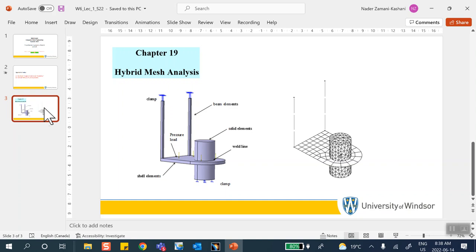Never mind, we're going to talk about that later on. You have a choice of making these things exactly like it is and then start cutting it, but just be aware that the split that you use for cutting that cylinder is in part design, and the split that you use for cutting that sheet is in generative shape design.